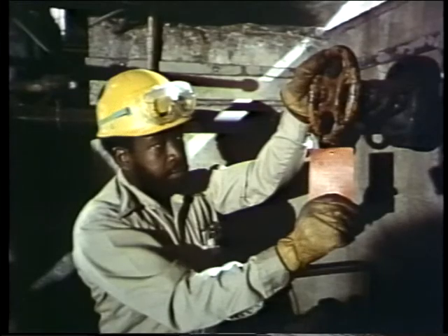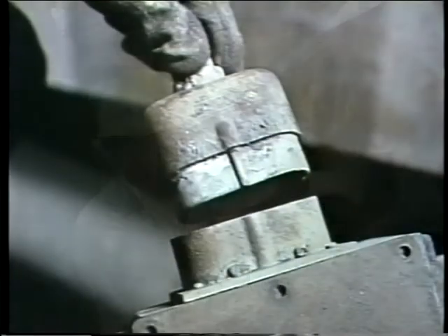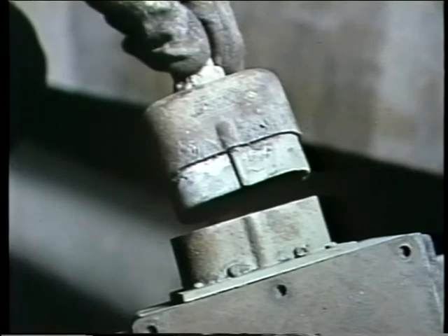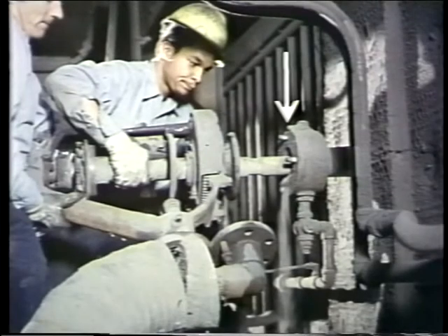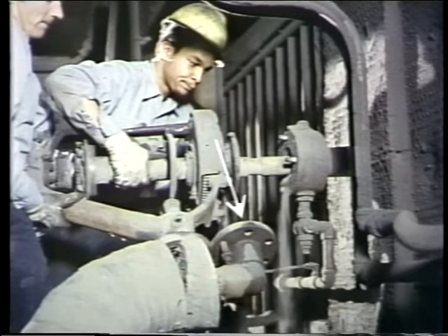First off, in order to do a detailed teardown for inspection and overhaul, you've got to remove the soot blower from its mounting. We'll see this done in 4 basic steps. These are, first, all the associated systems, such as the power supply to the blower drive and the source of the blowing medium, have to be tagged out as a safety precaution. Then, disconnecting the soot blower drive from its power source, loosening the blower from the mounting on the boiler wall, and separating the connection of the soot blower and the source of the blowing medium can all be done.